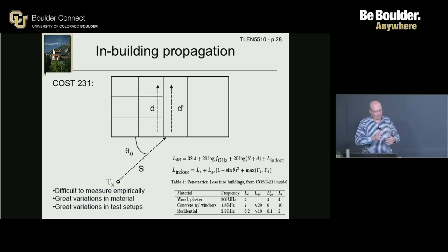Especially, again, I'm probably sounding like a broken record, but as you start going to 5G and you start building your expertise in propagation modeling at higher frequency, keep in mind what's around. Because I'm sure your boss will ask you, well, it's all very well, but what if I bid on that 28 gigahertz block now that the FCC is auctioning, but how well is it going to penetrate into homes?